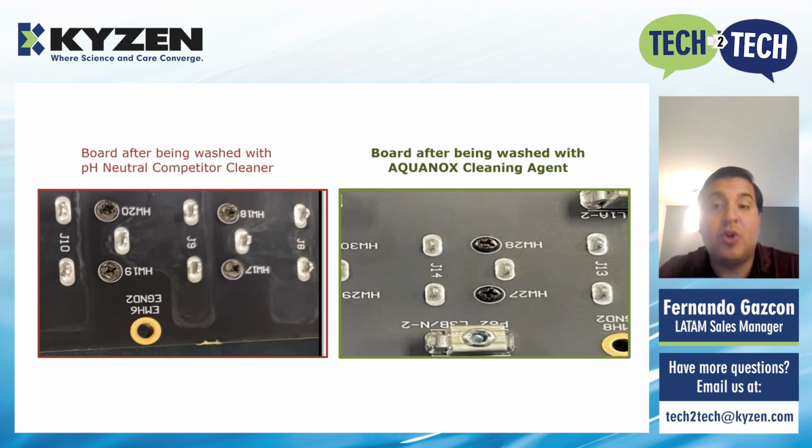Just by switching to the correct cleaning agent, the white flux stains that they had been experiencing for the past years using the pH-neutral competitor cleaner disappeared completely from their board surface. This was very surprising to the CM, who had already identified this as a usual defect on the board and thought it to be impossible to fix. Needless to say, the CM was very happy with these promising cleaning results.